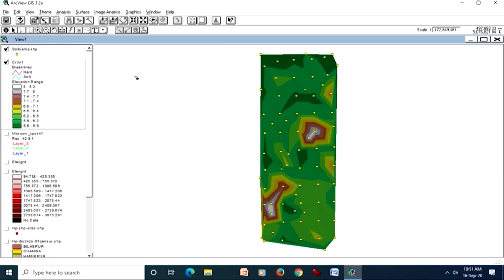And wherever you have a smaller number of mass points, larger triangles may be formed. And this is what you are seeing here: in this part of our TIN, we have points which are very closely associated as compared to these 4 points.